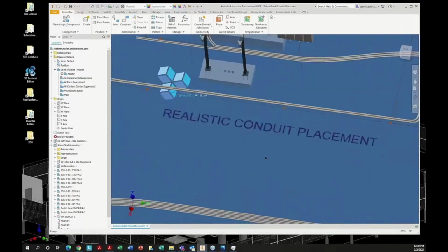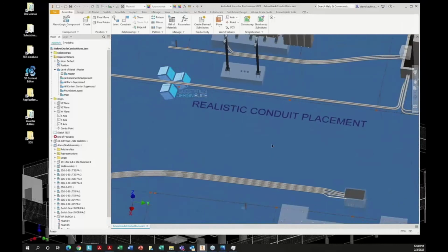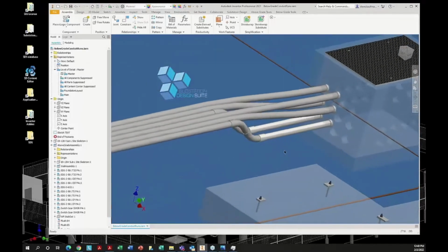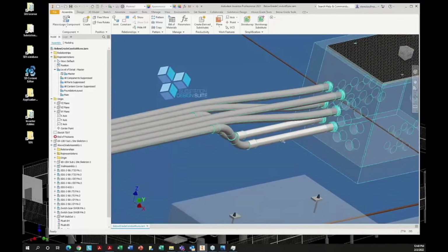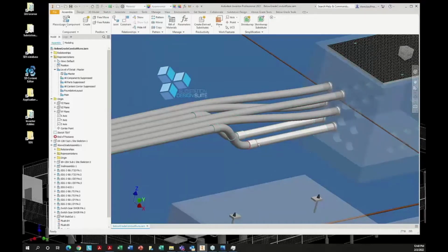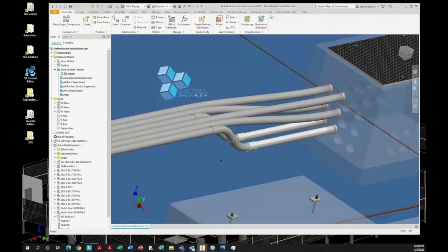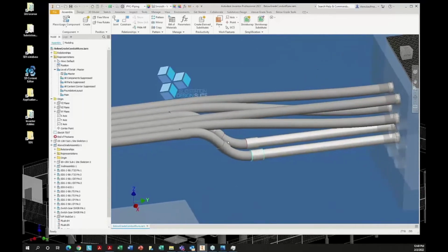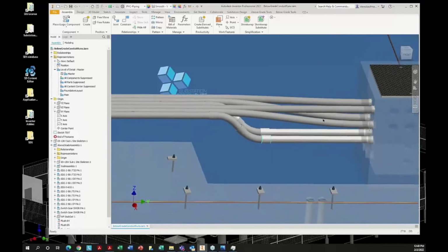And I'm talking a realistic conduit placement here. So in this case, I have my conduit runs here. I am using the steel pieces here. Let's go into part priority. I got my pieces coming in here, not necessarily steel, but they're bending up and I'm using the elbows. So where it's deep enough to use an elbow, I'm going to use my elbow. When it's a little bit shallow, I'm going to think they're going to dig it out and place it accordingly.